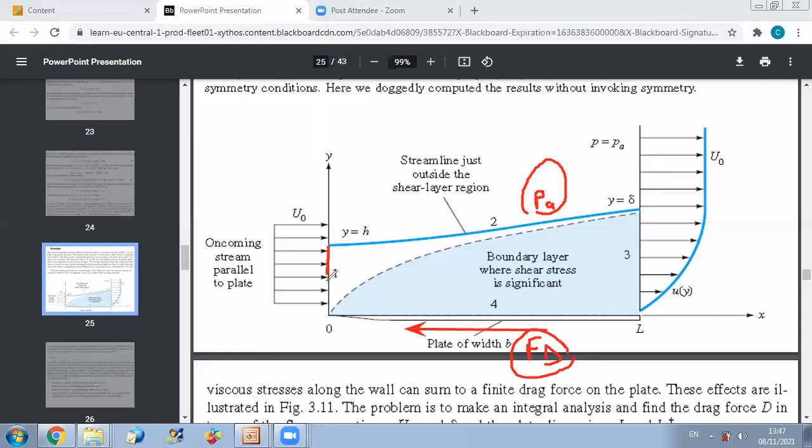we should consider inlets and outlets. So here we have one inlet at section 1, and it's a uniform inlet of velocity u0. And we have an outlet at section 2, but what is challenging about this outlet is that the velocity is changing. It's not a constant. So we have a certain profile for velocity, okay? And in order to be able to get the momentum flux at the outlet, we need to get u as a function of y and integrate it, okay? Now, how to do this?